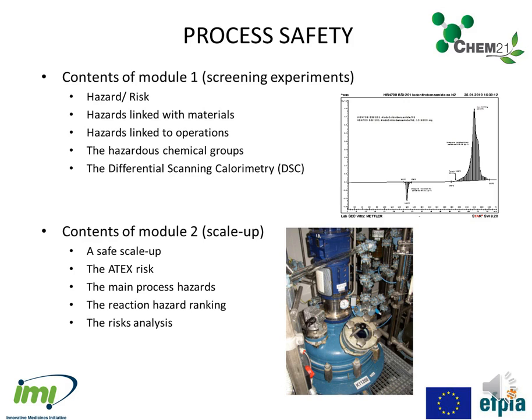The second module is dedicated to scale-up, mainly in kilolab and pilot plant. How to conduct a safe scale-up, the explosive atmospheres, the main process hazards, the ranking of reaction hazard, and the risk analysis.